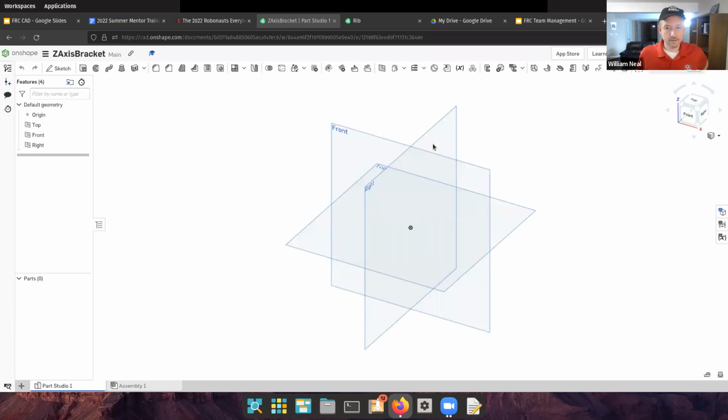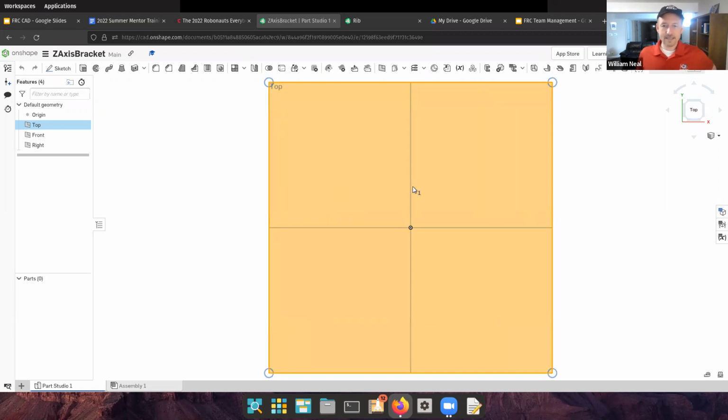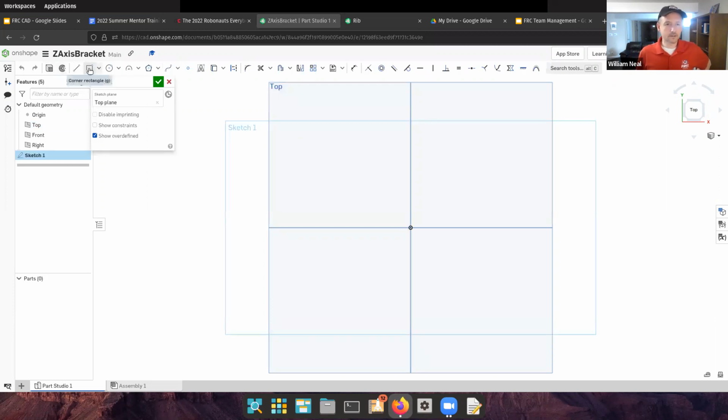Okay, and now I'm selecting my desktop plane with my left button and choose the top view. So I'm looking straight down upon my desktop and create a sketch. This particular feature will just have some rectangles and some circles. Start with my origin and put this up here, just like this. And if I recall correctly, this piece has about a certain dimension of width and length that I will specify using my dimension tool.